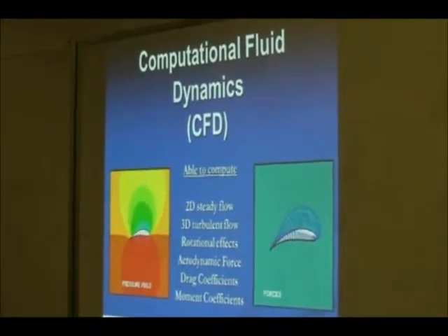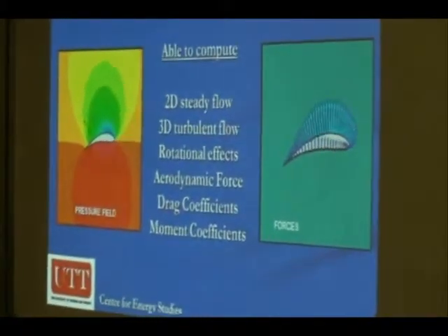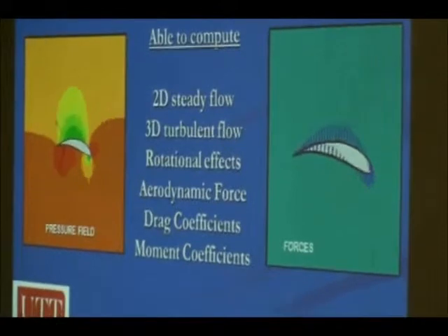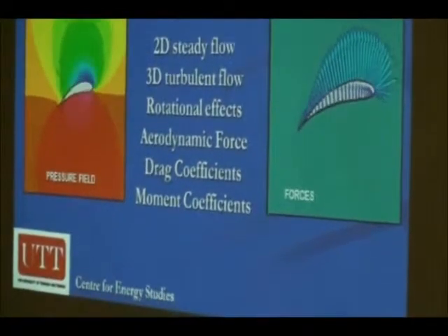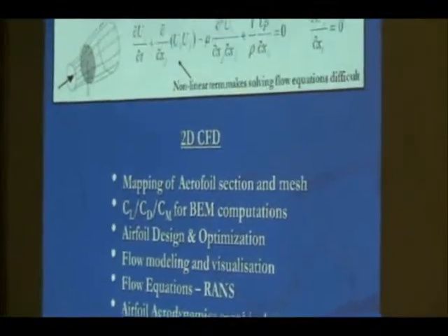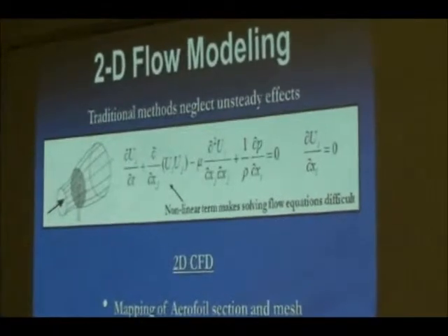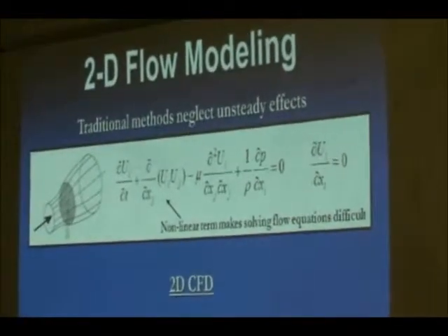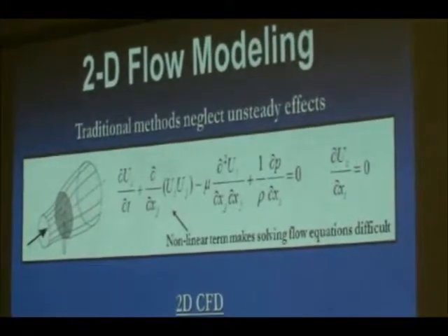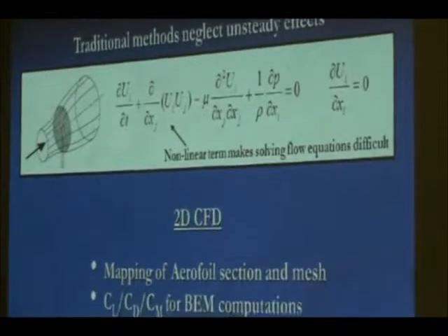With CFD, we're able to compute the 2D steady flow effects, 3D turbulent flow effects, rotational effects, the aerodynamic force, and coefficients. We'll be looking firstly at the 2D model. This allows us to map the airfoil section and its mesh, gives us computations for the coefficients of lift, drag, and moments,